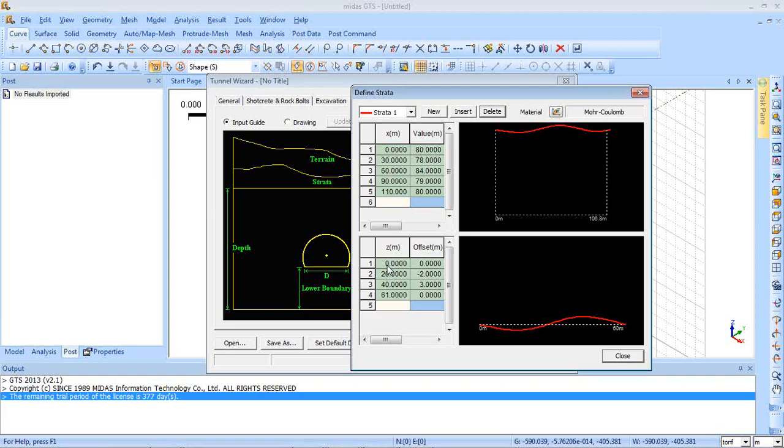Here we have one question: if we use steel or beam for shoring of tunnel at specific intervals, how can we define it in the software? We can use steel arch beams for shoring of tunnel at specific locations. So you can define it as a beam, and in the material property you can assign it the properties of steel.